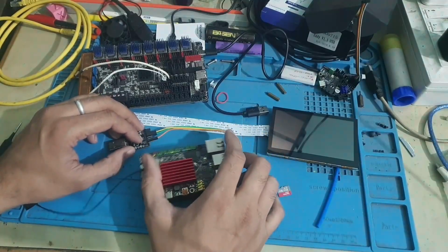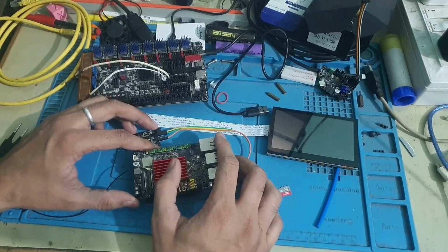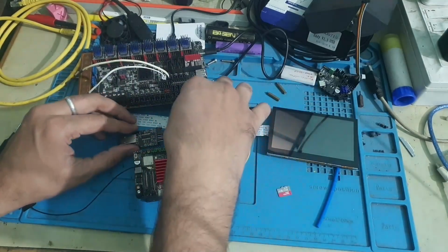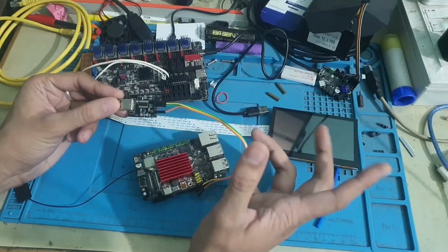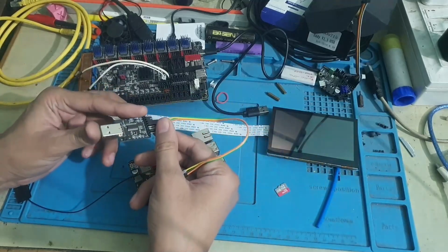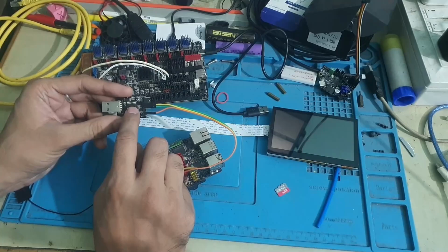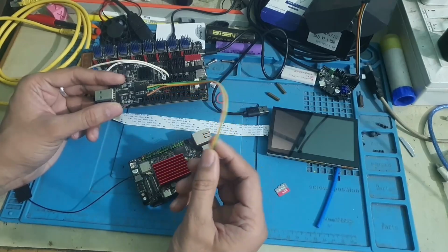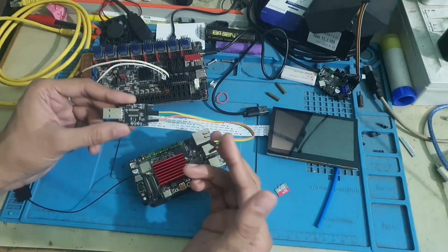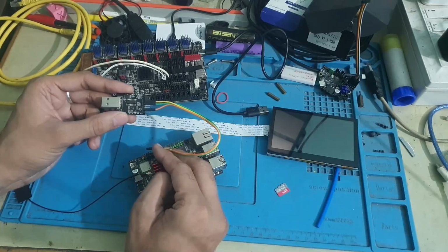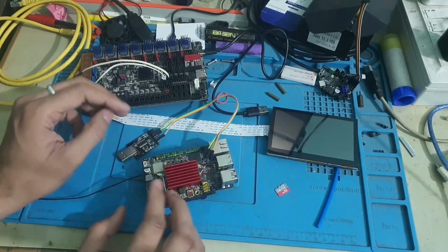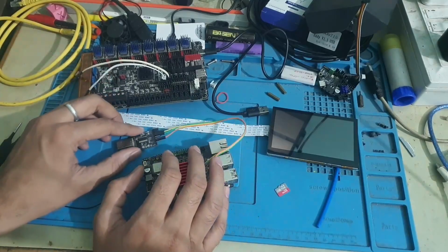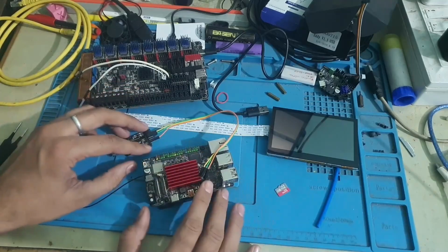If you're not able to access the LAN cable or something, and you want to use USB to serial, you need some kind of device, maybe a CH340, a chip that converts USB to serial. You need to connect it on the Pi, so you can log into the terminal and edit some stuff there.